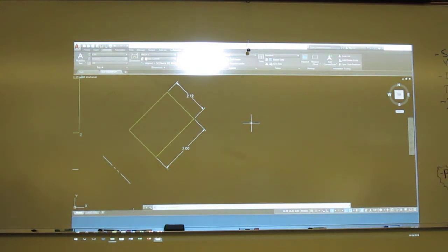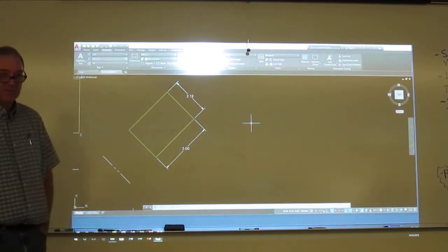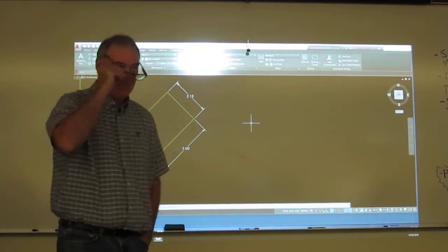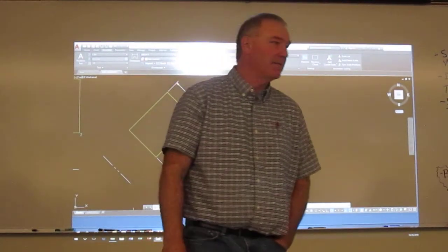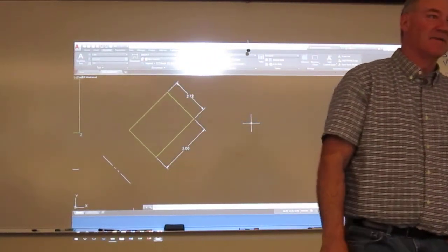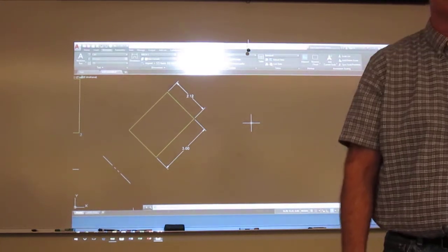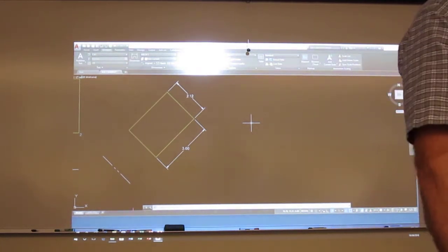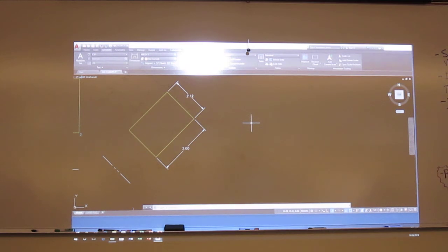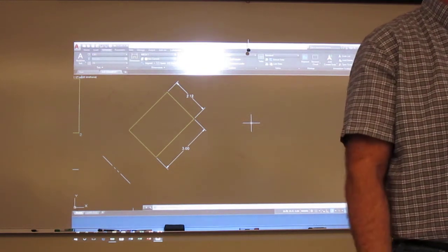Do you not do the other, because that's a top view? No, it's not. It's an auxiliary view. It's a primary depth auxiliary view. So it's only that plane. That's all we needed. The glass box, our standard 6 views, did a very nice job on the rest of it.